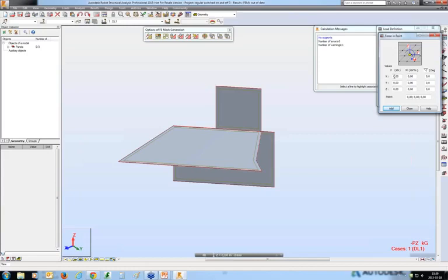This has the shortcoming that when you redefine the mesh, you will need to do it again: select the newly generated nodes and apply the supports. Therefore, if you want to indicate that the entire edge of the panel is supported, it is recommended to apply a linear support to this edge, and then you do not have to think about this definition again.